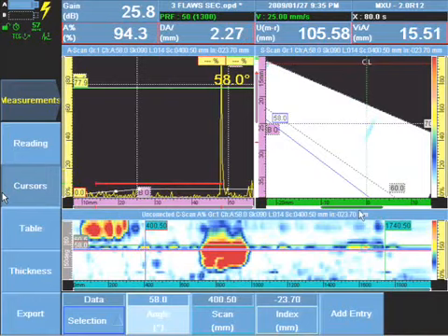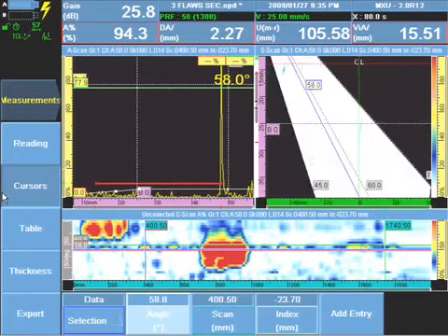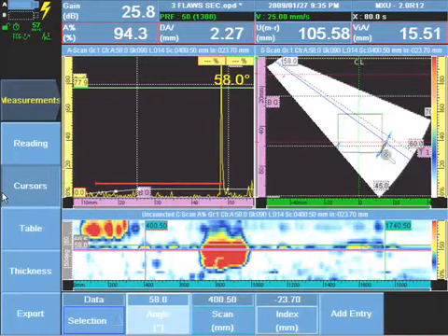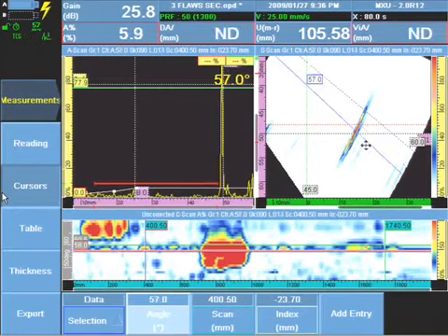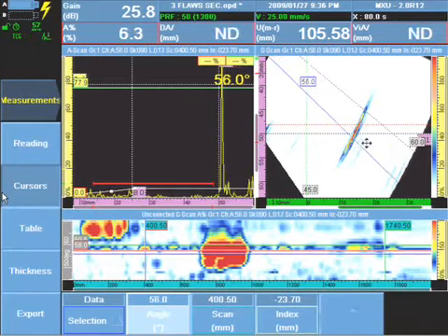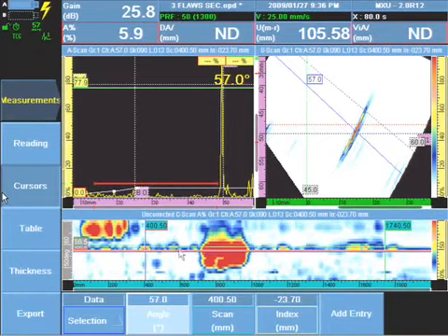Here we have an indication plotting directly to the cap on the end of our second leg. We have the first skip, B0, the end of the second skip, T1, and we have an indication very typical of cap geometry plotting right to T1, typical throughout the C-scan.